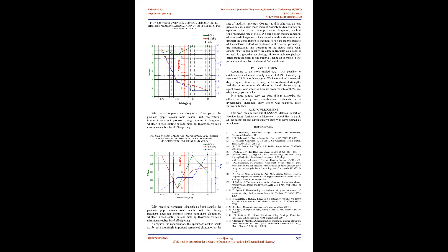B. Mechanical tests, Rm, E. The various cast specimens will serve us mainly to determine the mechanical characteristics of this alloy. For this, we carried out tensile tests. Then, in the analysis of the results, we will only consider the test pieces giving consistent data, and we will take an average of these values, considering the standard deviation and the dispersion of the measurements.